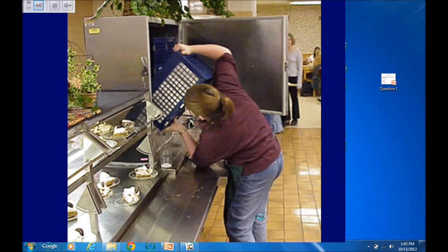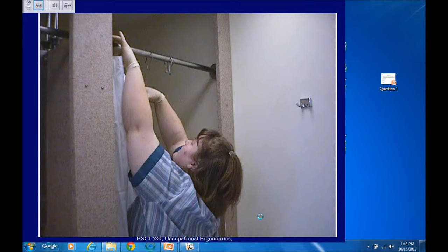Right here on Purdue's campus, a 5-gallon container. We still do this today. Very awkward posture trying to lift this up here, a female trying to do this work. And it's a significant amount of weight. Milk is very much like water, so you basically use 5 gallons, and you can do the math very quickly that you're up a little over 40 pounds on this. An easier thing would be to have a tray to be able to come up to this and slide that right into position and pull it out. In this case, if it slips out of her hand, she's got an issue.